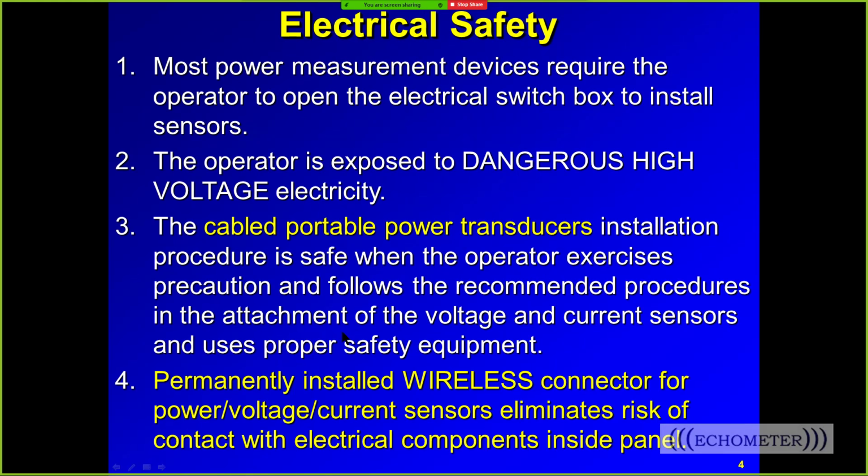Now, safety is important, and you need to be certified to open the power panel and connect the power probes, and you should always exercise safety and check that the panel is not hot. Disconnect the power. Never put your hands inside the power panel. If there's something that looks bad inside, or if you think the power is not disconnected, or if you see a burnt area, you should call an electrician and get that repaired. Some companies don't allow their employees to open up the panel, and may even have to have an electrician open the panel.